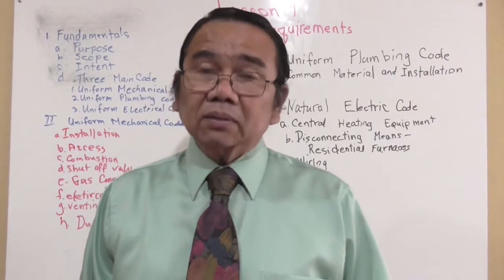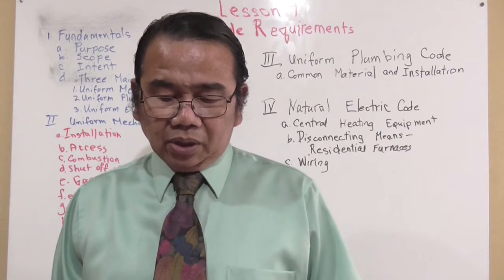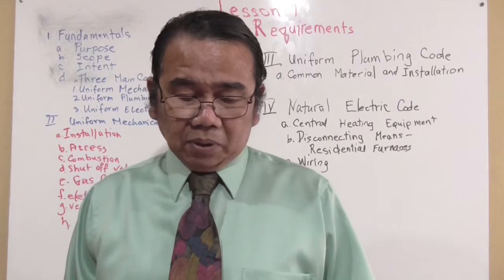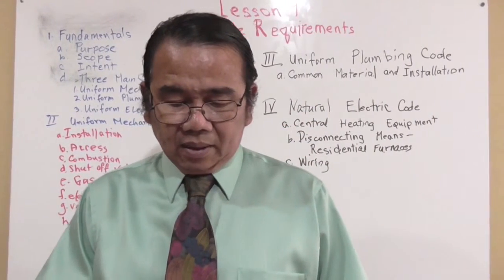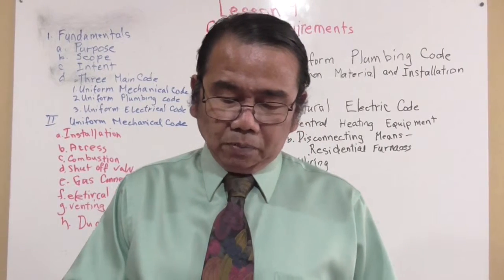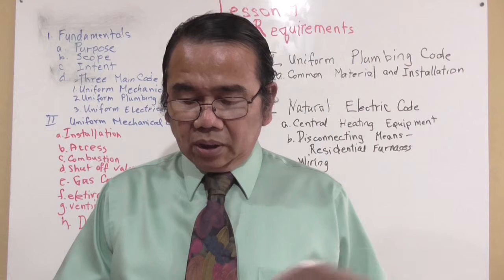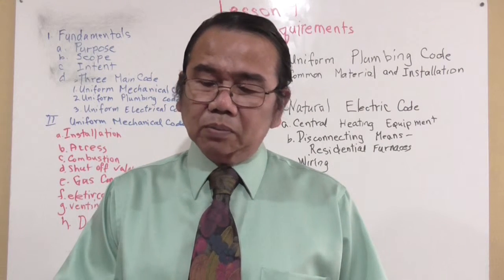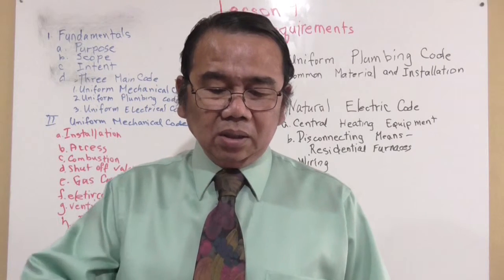Not longer than 3 feet. No concealed connectors or passing through walls, floors, partitions, or equipment cabinets. Properly sized. See uniform code table 3D1 or 3D2, and do not use copper. This is the uniform mechanical code section.